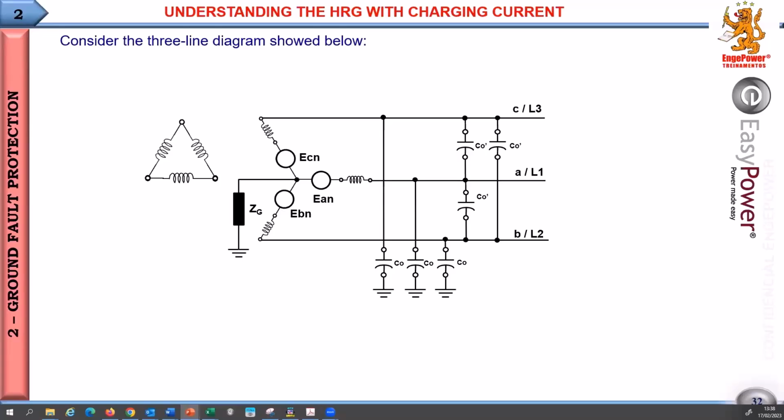We showed that we have these capacitances that are born with equipment, the trap capacitances. And also between the phases, we have capacitance. But these capacitances don't affect single line to ground faults, nor line to ground overvoltage.